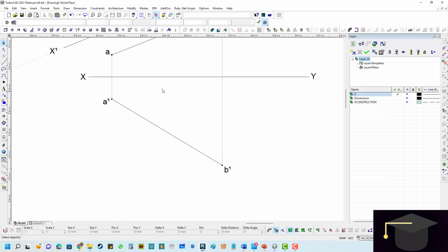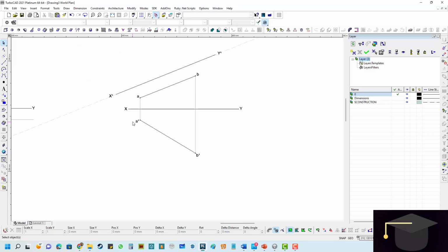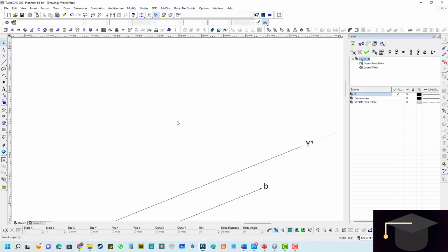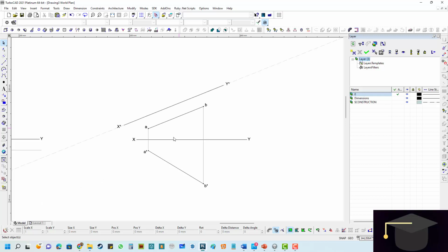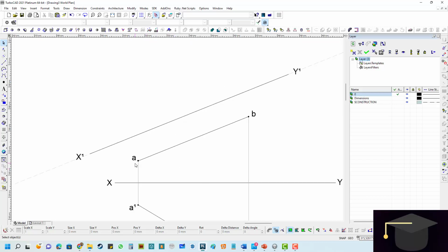So this is my actual horizontal plane, which is the top view. We want to determine the true length of line A1, B1 and project it into this open space. Once again, as you have most likely learned already, we're going to use the measure, skip, measure method to do that. But before we get there, let's make sure that we do the projections from reference points A and B correctly. For that, we can also use a tool here on CAD.